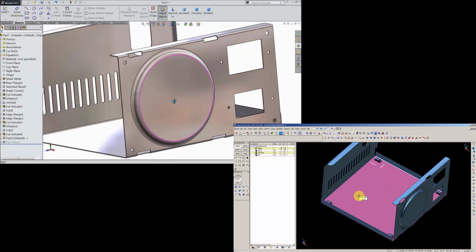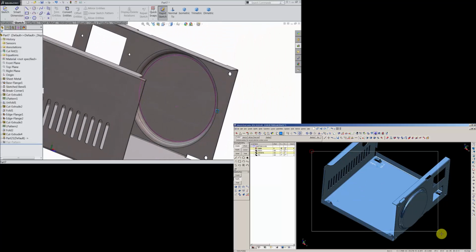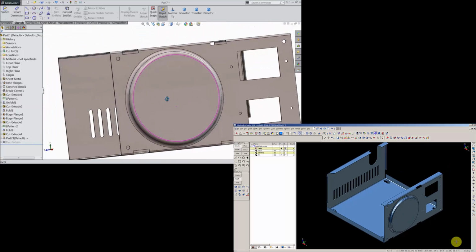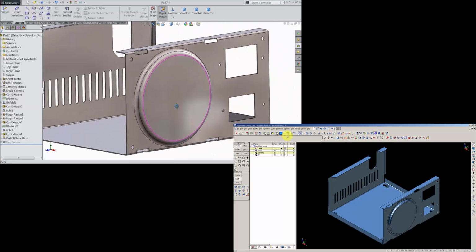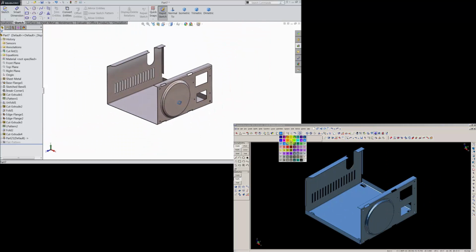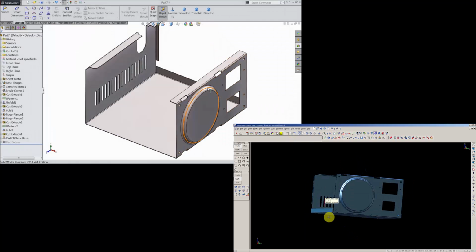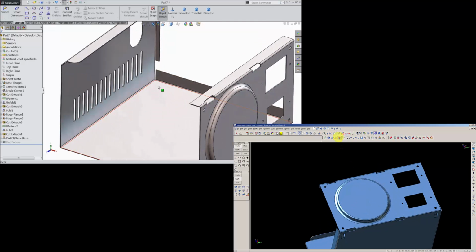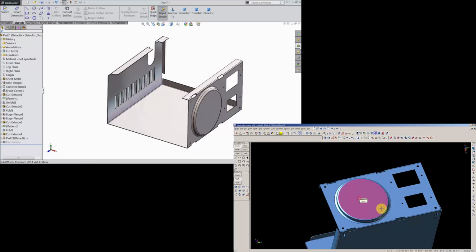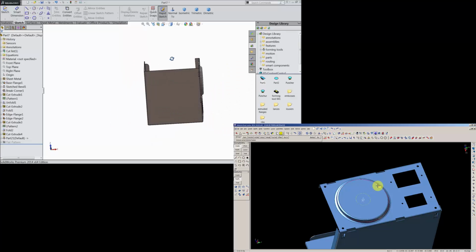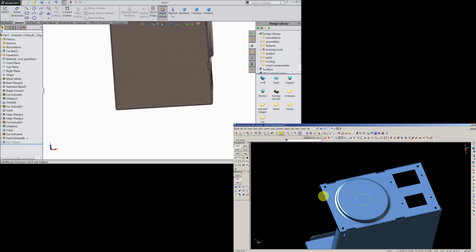Now see, this is the emboss part. How we make the emboss with the help of emboss tool. You can see it here. Now here we will fix our lenses or forming tool in this face. So just go to design library, forming tools, and here part 1 we created. So just reverse this and we will fix reverse.